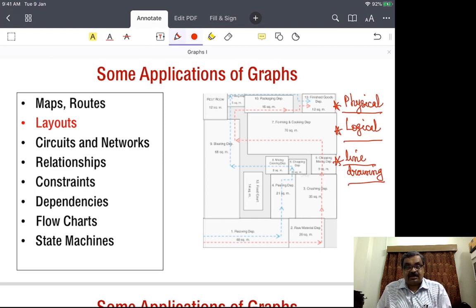And we will just see how in each of these cases the graph is formed. Let us look at a physical layout. Then for every such rectangle, we would keep one node for a particular rectangle. So every node would depict a rectangle, and on every node we could mention the location of the rectangle. Because we are doing a physical layout, we could mention the location by the center of the rectangle, and along with it we would give two labels: the center of the rectangle and the dimensions of the rectangle.